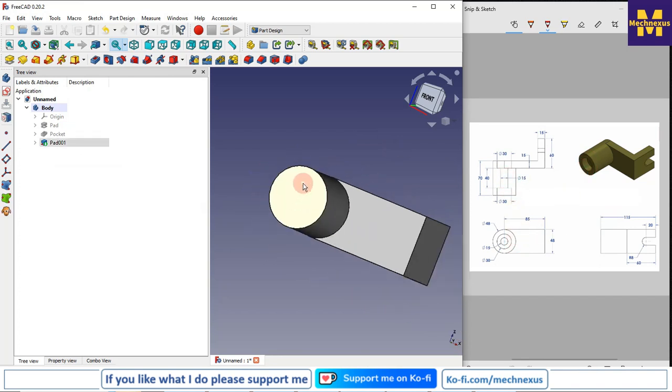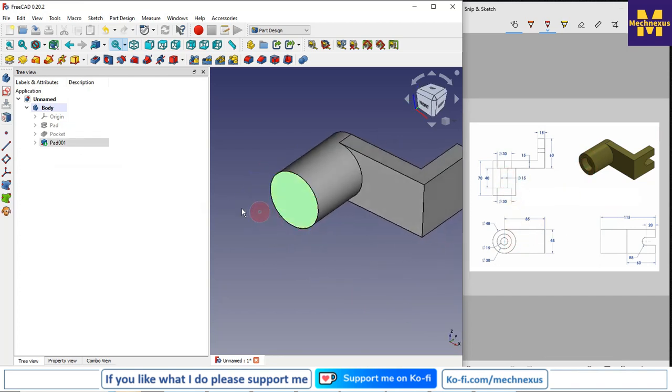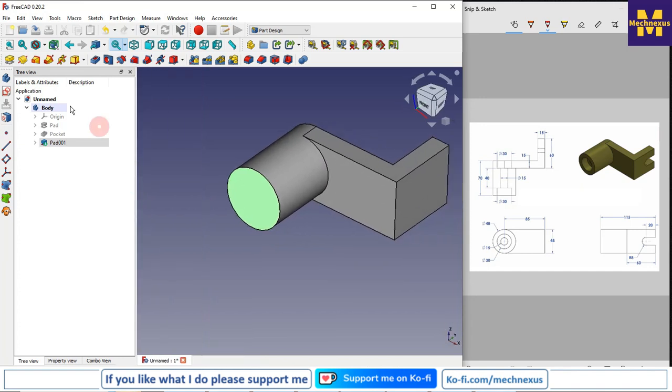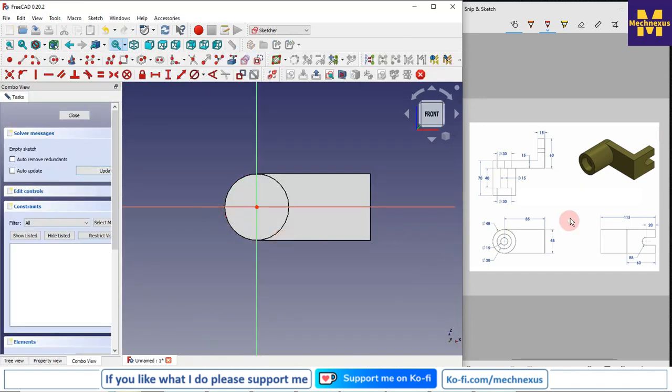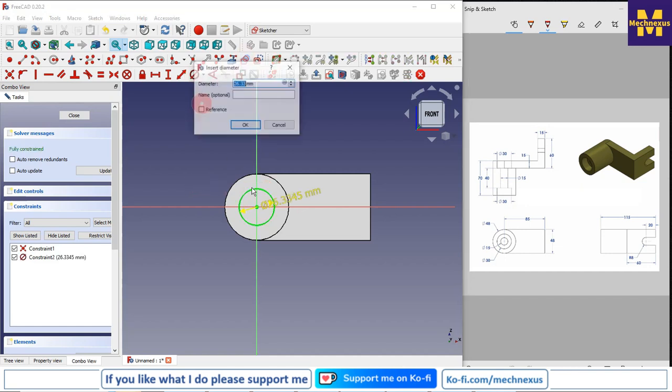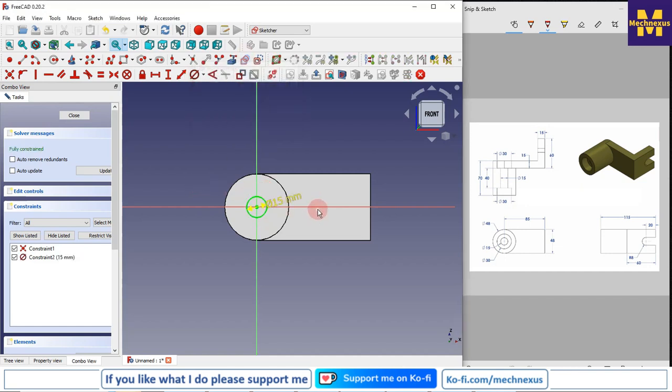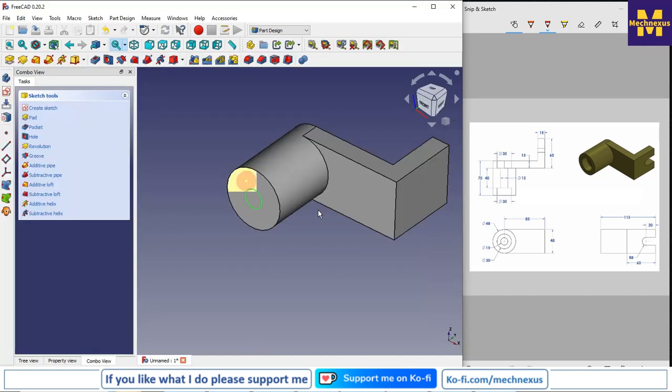For counter bore holes we will select this face and create a sketch. Here our minimum diameter is 15, so we will create a circle and assign it diameter 15. Say close.